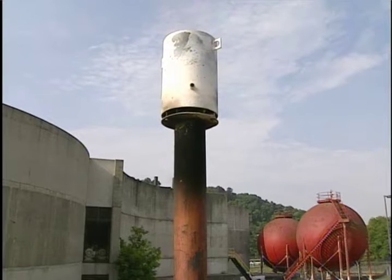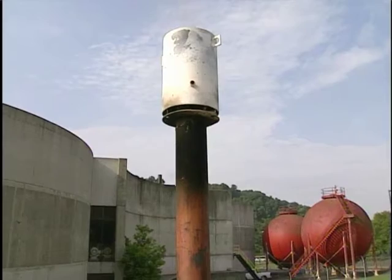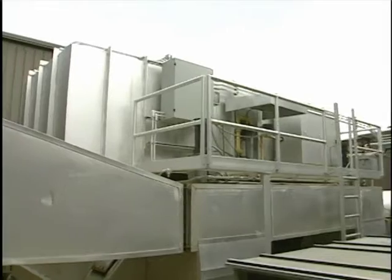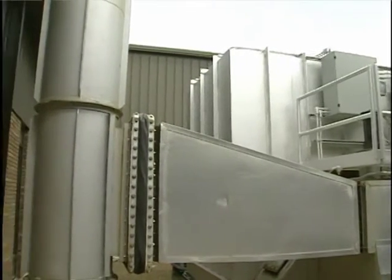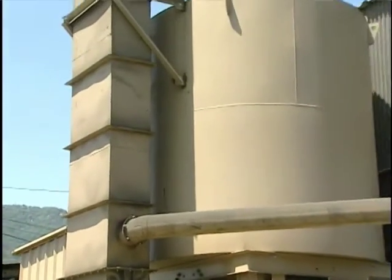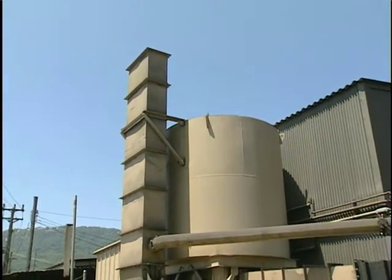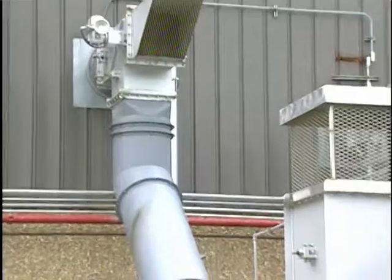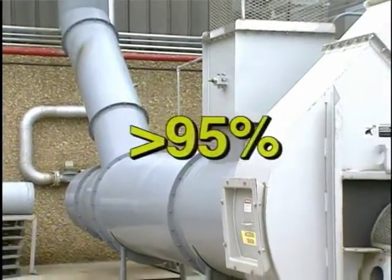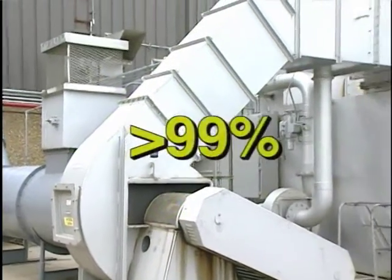In vapor incineration processes, organic contaminants are removed from a gas stream by oxidizing them to other compounds. If the organic compounds are composed of carbon and hydrogen, then the products of that oxidation are carbon dioxide and water vapor. However, if the organic materials contain chlorine, fluorine, or sulfur, then hydrochloric acid vapor, hydrofluoric acid vapor, sulfur dioxide, or other compounds may be formed. In general, incinerators are capable of destruction efficiencies greater than 95%. Some incinerator designs have destruction efficiencies greater than 99%.